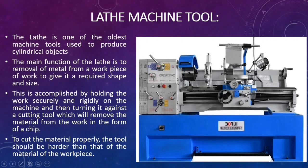The cutting tool is placed on the carriage. To cut the material properly, the tool should be harder than the material of the workpiece. That is very important. If the job is mild steel, then you have to use a high speed steel or carbide cutting tool, because it is harder than mild steel. Cutting tools harder than the metal can cut the softer materials.